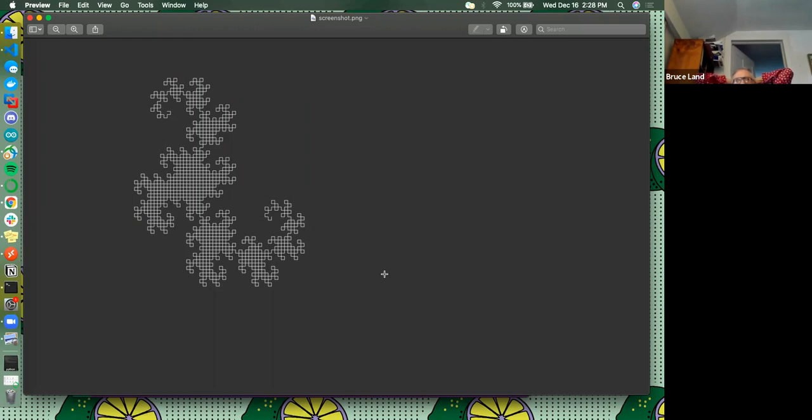The clock rate of your laptop is probably between 2 and 3 gigahertz, and the clock rate of the FPGA is 50 megahertz. So it's impressive that you're a factor of 20 faster. Now, it's hard to compare those because Python's an interpreter and who knows what it's doing. Still, in terms of total energy used, the FPGA is a clear winner because it's probably running at maybe 500 milliwatts, and your laptop is probably running at 20 watts.